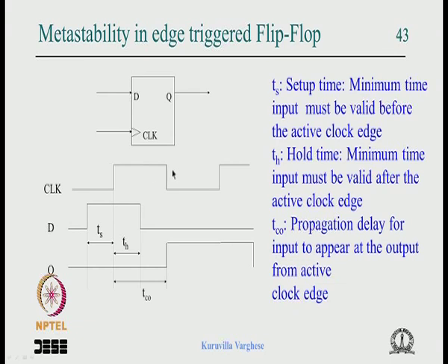You also would have studied a master slave flip flop which works as an edge triggered flip flop, because most of you would have learned the master and slave configuration, and that is an essential logic circuit for the edge triggered flip flop. Most textbooks give two cross coupled latches one after the other.